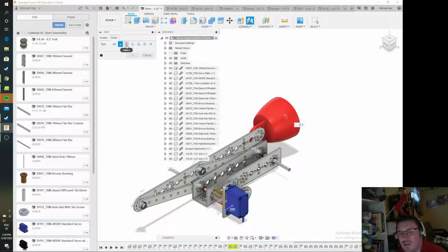It's somewhat like a revolute. It will move from one side to the other. It will have a minimum and a maximum movement. It makes a lot of sense. All you would do is you would take a slider joint, and you would take a revolute joint, and then you would motion link the slider joint to the revolute joint, or vice versa. That way, when the pinion gear moves, the rack gear will move in concert with it. Does that make sense? Okay. So instead of motion linking two revolutes together, you're just motion linking a revolute to a slider.